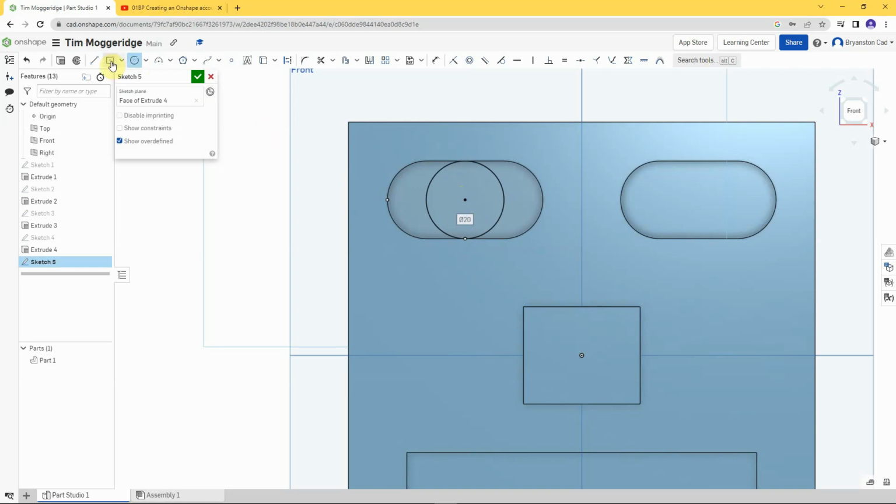I'm now going to use the line tool, and I'm going to move up to the top and draw a line by clicking and holding the mouse button, coming down to the bottom. So I've just drawn a line. If you click and click, I'll show you over here in space. If I left click and left click and left click, it keeps putting in a line until I right click and go escape line, or I press escape. So if you do that, you can just press escape.